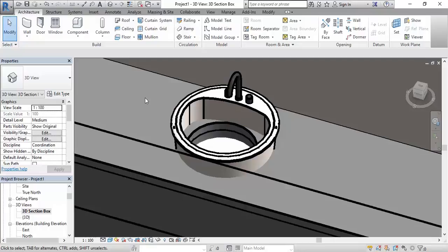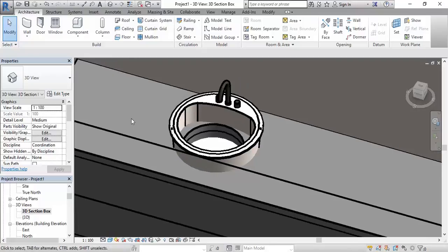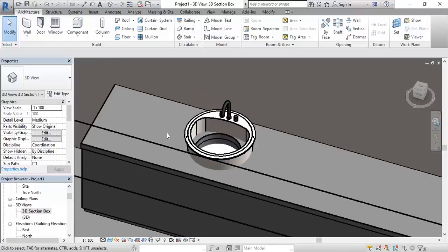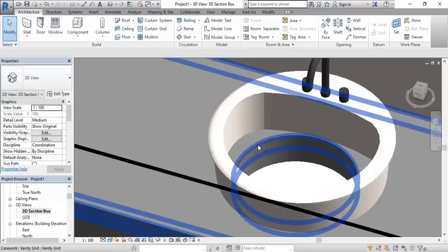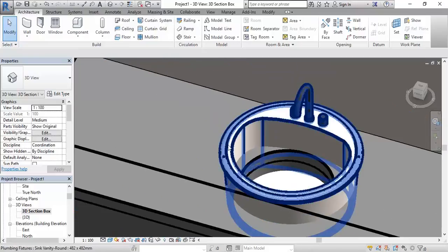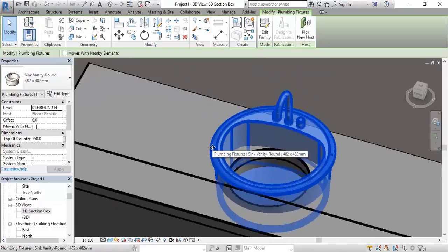And these are the things when you're designing your units that you need to factor in as well. So if you're designing a bench top, which you'll be doing all the time, you need to give the joinery drawings to the cabinet makers with the cutouts worked out. They wouldn't cut them until they get on site, but you definitely would need to locate them on their drawings. And it gives you a good idea how these things are made. So you can see here I've made the cutout, and we can obviously see that it's not big enough, but also the sink itself isn't at the right height.